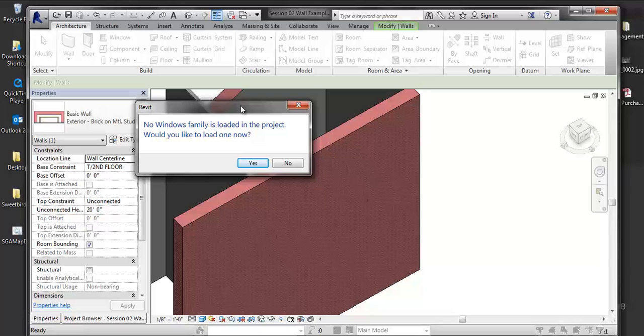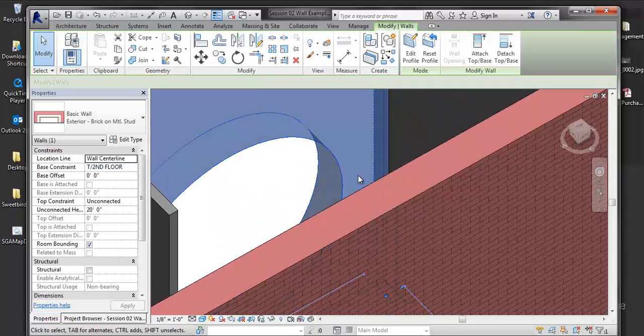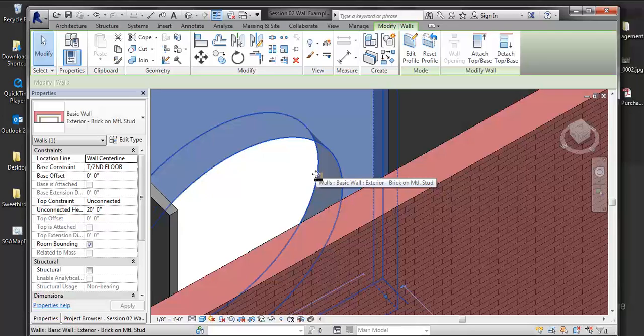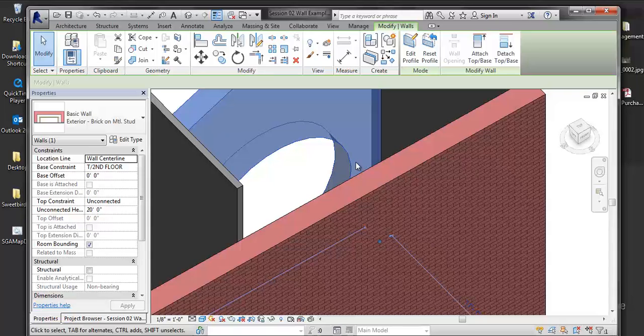Let's take this further. If I wanted a material property to show, so for example, if I have a wall that has that insert and I want to be able to see that layer of brick as a single course of brick in a rendering or whatever, if that's important, then what I would do is model it as two walls on top of each other. One the backup wall and one the finished wall. And then I would cut both. That way I can really control that layer.